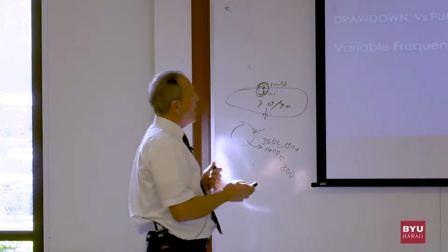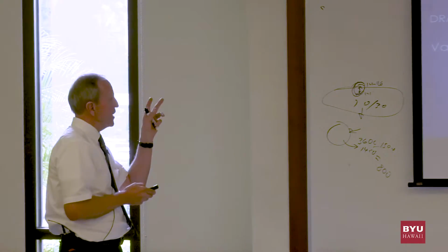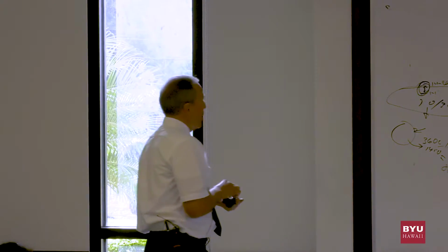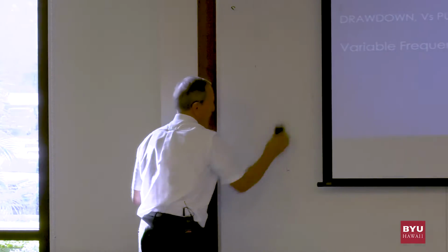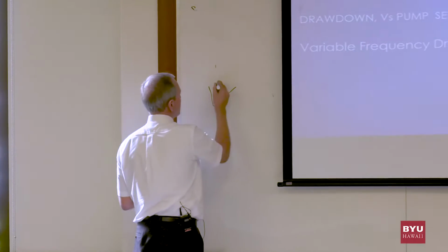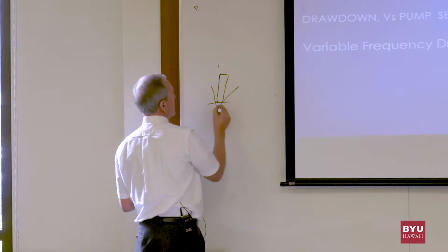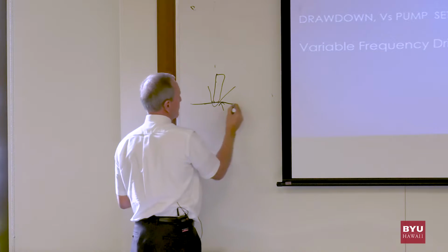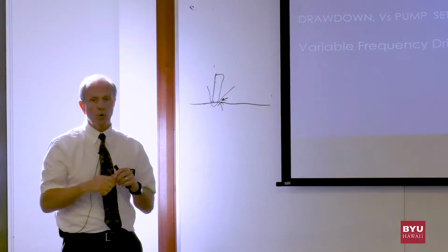I remember that this is how it was. I could look at this. I knew the drawdown. I knew the GPMs. I knew what the pump setting was. One thing you don't want to do is cavitate a pump. Maybe no one knows what cavitate a pump means. When your drawdown comes here and your pump is here, you never want the water in your wells, in your aquifer, to go this low. If you don't have any water coming into your pump, you blow up your pump.